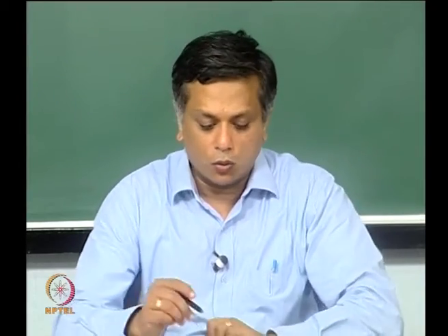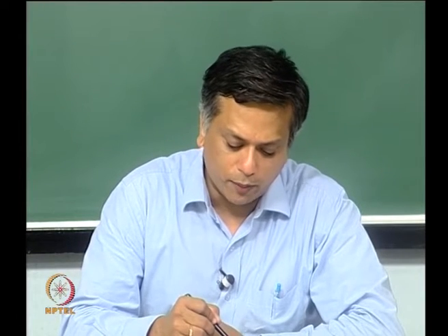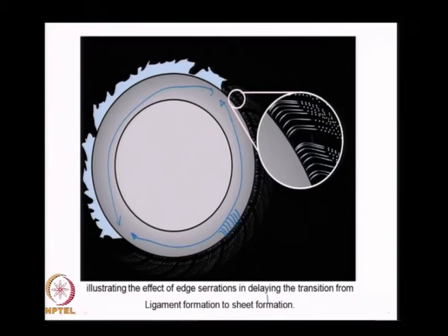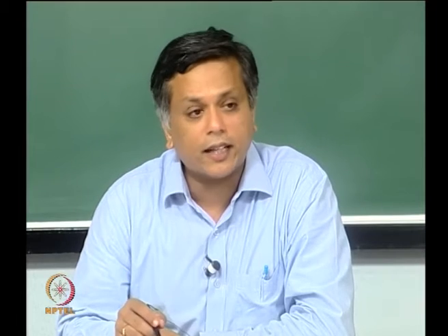Now, what is also shown in this schematic is where if I take the cup and do not put these grooves, what I end up getting is actual film spilling over that looks like is shown in this schematic. So, it is like a liquid film itself that spills over the edge of the cup, that is not atomized at the point where it spills over. The problem with that is now I have no control over the drop size as much as I had in the other design.